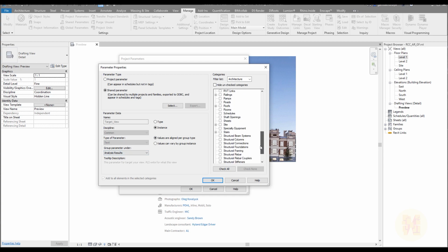And here we will use the views. This parameter we will use not only for the views, we will use it for the legends, sheets too. Let me find the legends here. For everything what we wanna combine together. And we also wanna use it for the schedules. Where are the schedules? It's somewhere here. Schedules here. Okay. Sheets already here, and detail view, something like that.